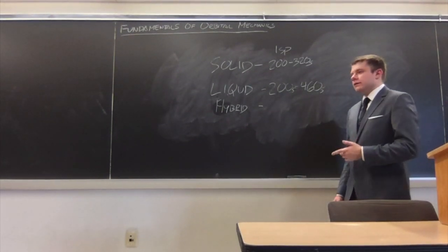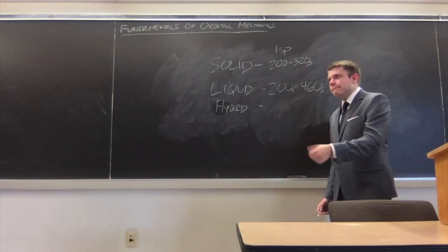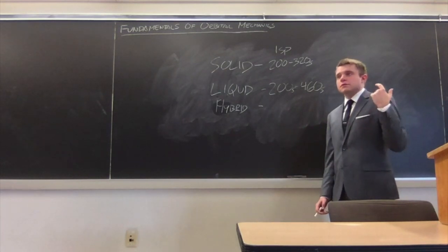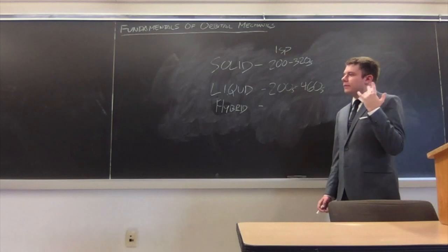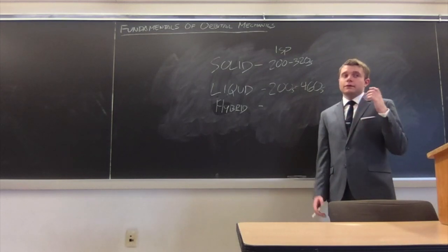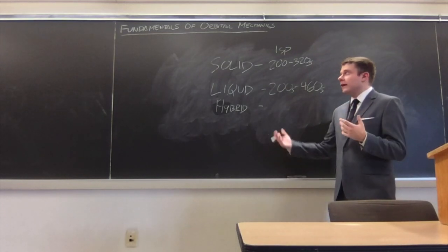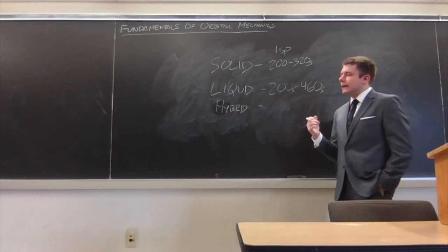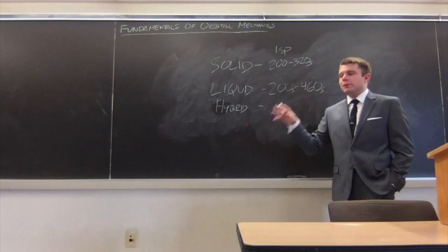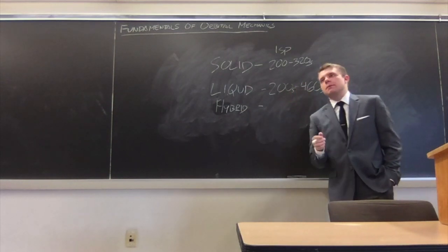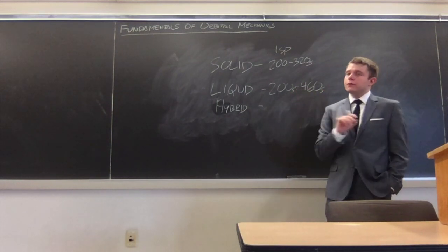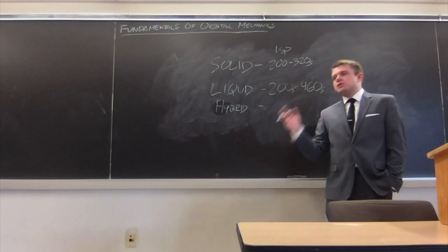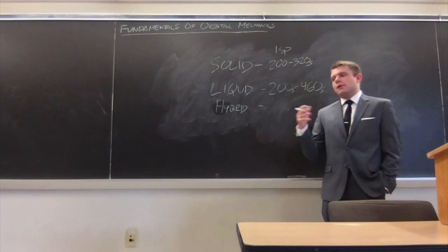Liquid motors, on the other hand, are very nice. You can throttle them, you can turn them on and off, which means you can fire them multiple times. The propellants are generally easier to handle. You need an ignition system that's a little more complicated, but generally speaking, it's all very nice and relatively benign, except that the engines themselves are incredible masterworks of engineering, because you need to make sure you're delivering your fuel and your oxidizer in just the right proportions, just the right amounts, in just the right way, so that they're all together in the right place.